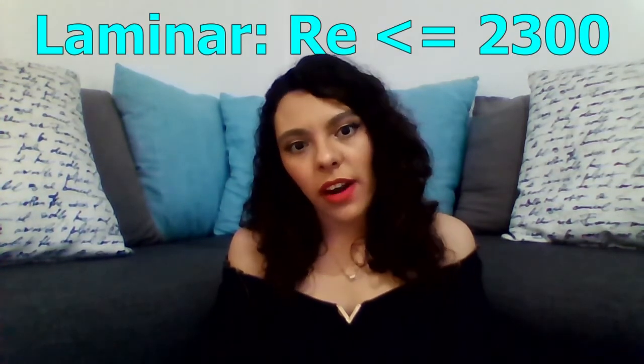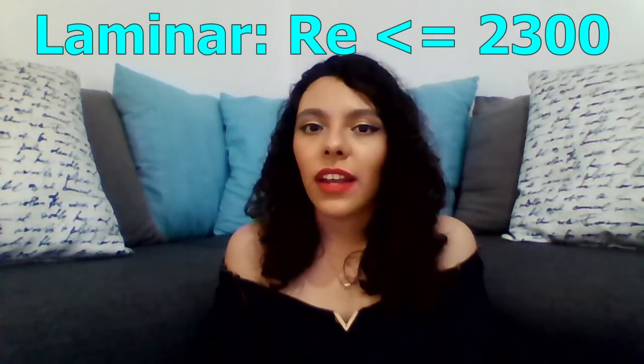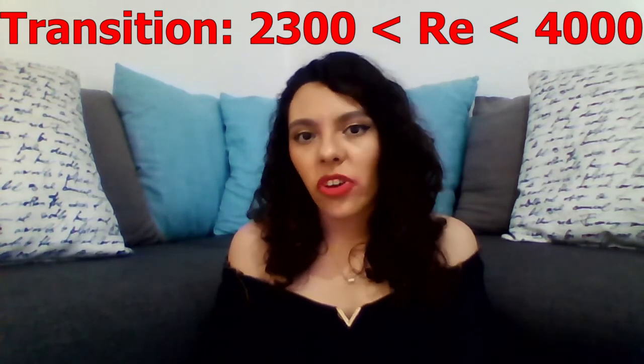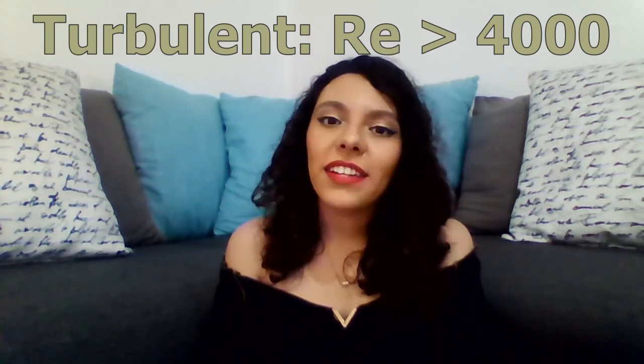The Reynolds number is dimensionless and indicates the type of flow we have. Either laminar, when the Reynolds number is less than or equal to 2300, in transition, when it is between 2300 and 4000, and turbulent, when it's greater than 4000.